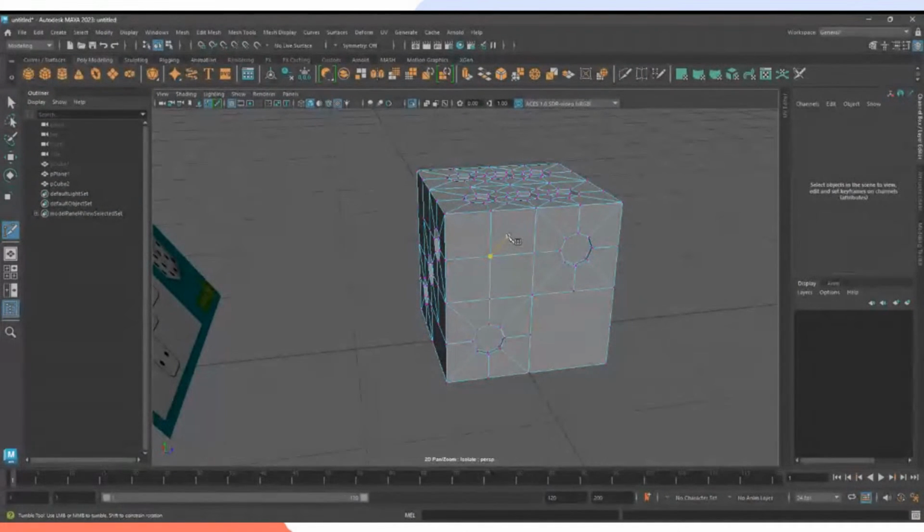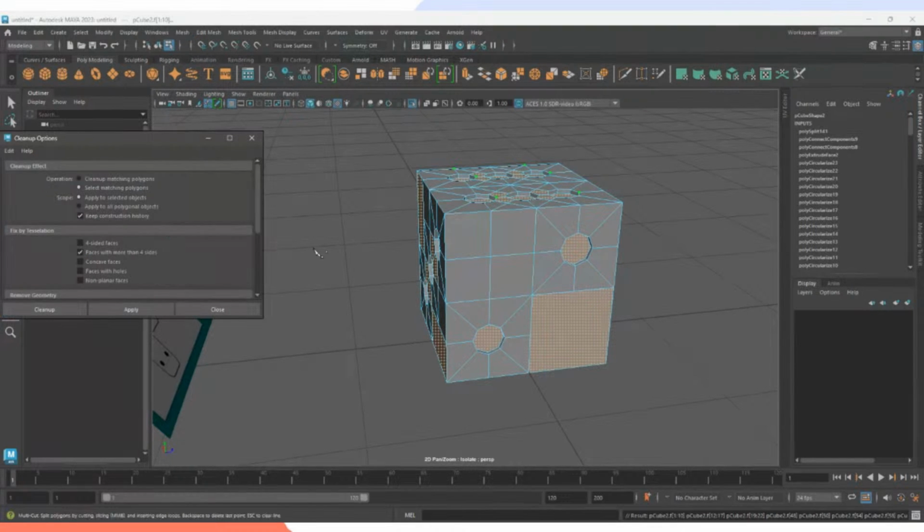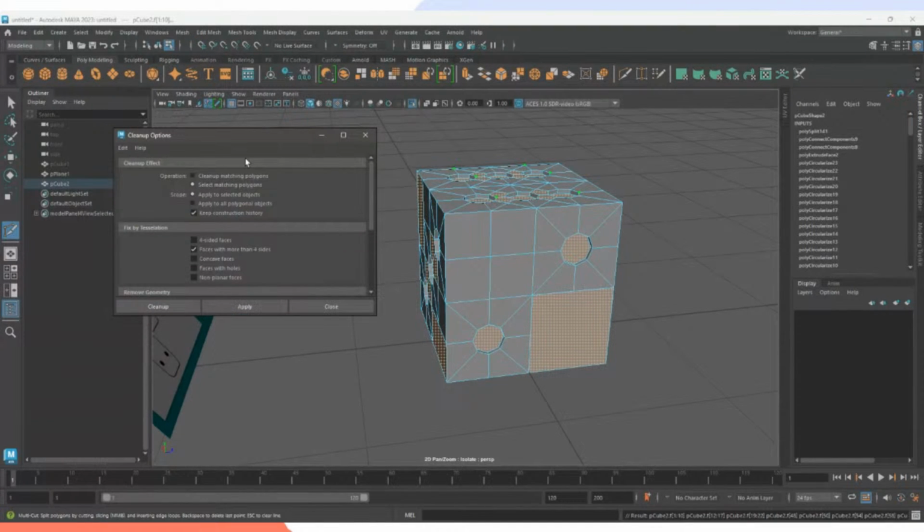But in case there's more that you actually don't know of, how are we gonna make it visible? One of the biggest ways you can do it is by pressing Mesh, and then Cleanup. But it might not be set up the way you want, because if you just press Cleanup and it just does it, it might not do this. It might do something else. That's why we have this icon here. This is basically the option box for each tool that we have here.